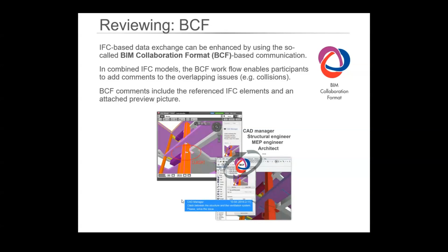So can we use Solibri to view BCF? Yes, you import the BCF, as that's the information that comes in alongside the 3D file. So it's more the 2D information, but it ties up to the 3D file. I don't think the BCF is a file you open in Solibri that brings the model. You have the model open, and then you bring the BCF into that file, and it brings all the data and knows where the places are in the model that data relates to.